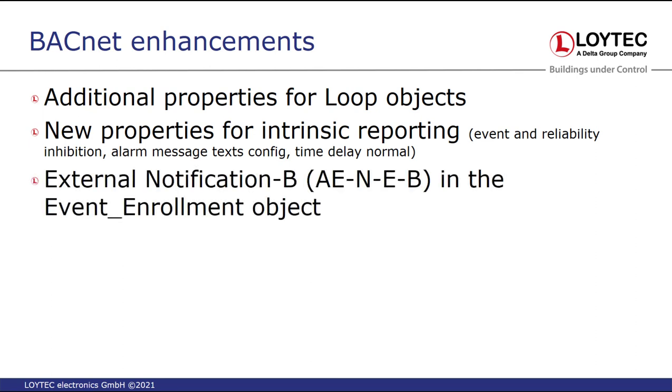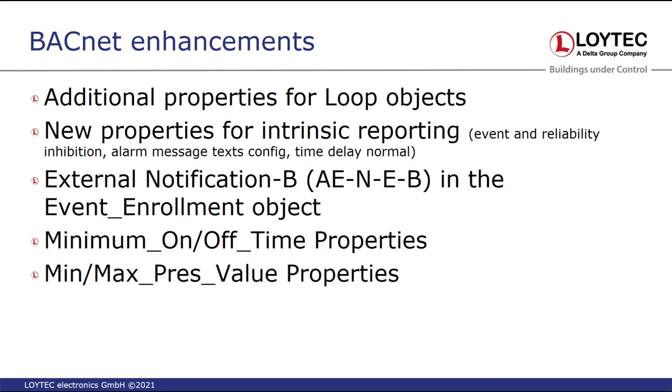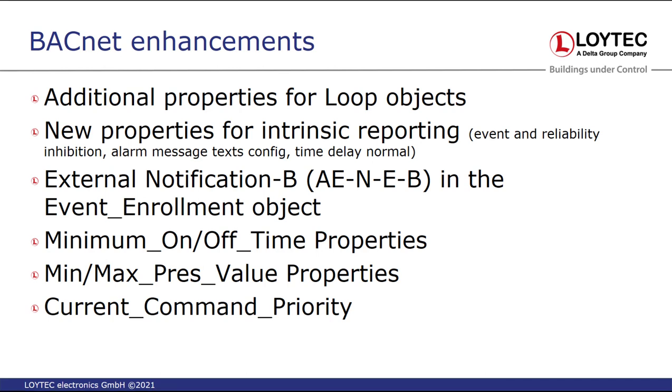An event enrollment object can now also monitor external properties from an external device. Commandable binary objects now support the minimum on/off time algorithm. The min-max present value properties for analog value objects are now supported. Current command priority for commandable objects is also now supported. This property is required in BACnet revision 1.15 in order to display the currently active command priorities.